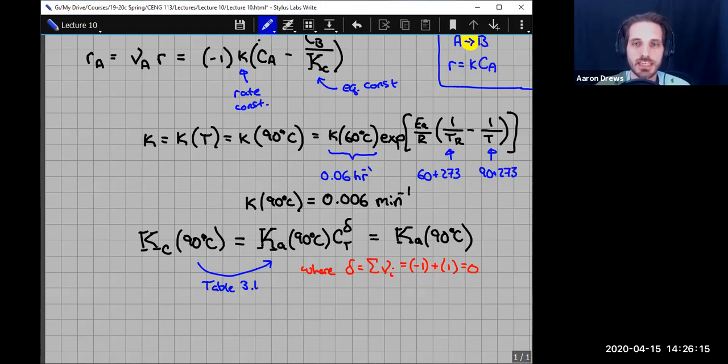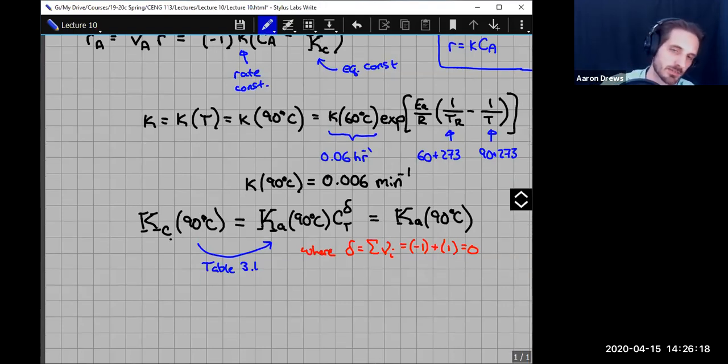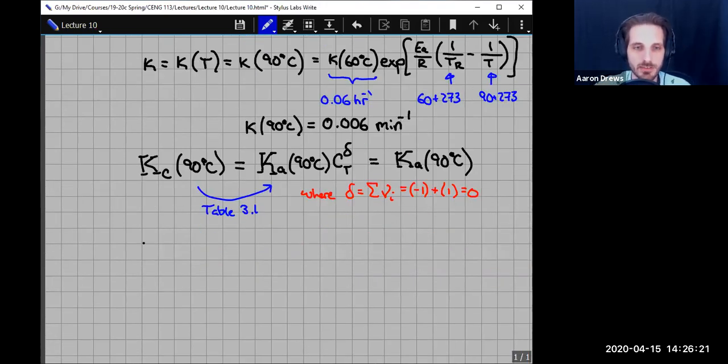So this particular Kc can be calculated from our shortcut K. So let's just continue it over here. K sub C is equal to K0, K1. Remember, these are all capital Ks because they're equilibrium constants. And so now I would have to go look up the enthalpies and the Gibbs energies of formation for orthoxylene and paraxylene in their liquid phase. Make sure you don't take the gas phase ones. They have to be in the liquid phase because our reactor is operating in the liquid phase. And if I were to calculate those, I would end up with 3.67.